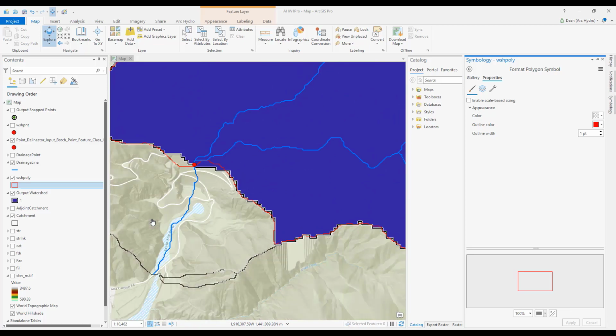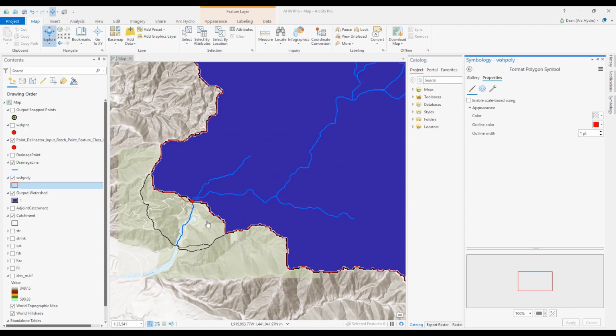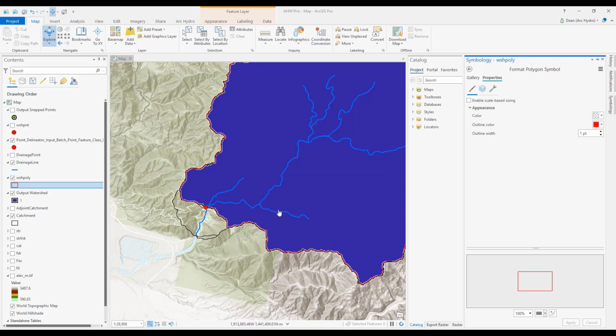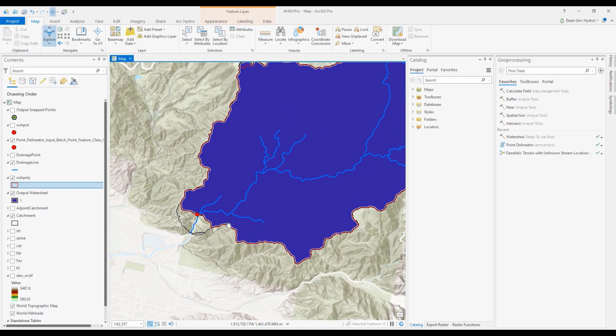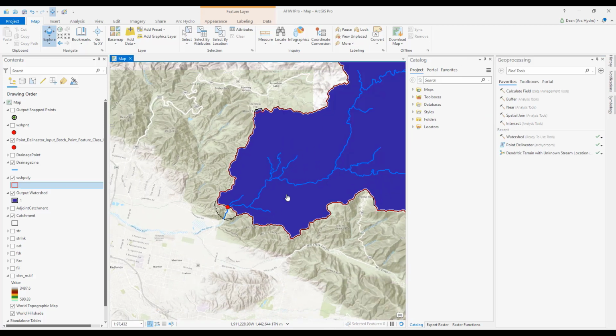Well, there are some differences that are very close. This is a result of using different resolution DEM and how they were pre-processed. The underlying terrain pre-processing and watershed delineation methodologies are both the same. Differences in results as a function of different data resolution and their interpretation is something that we will talk some more in the following webinars on hydrologic and hydraulic modeling.